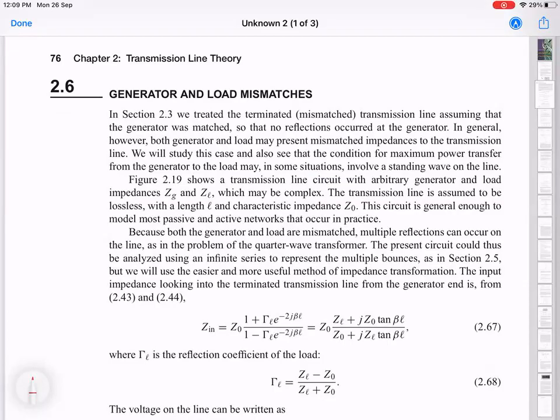So I want to finish up this basic discussion of how we think about waves propagating on a line today, and then introduce you to some of the standard transmission lines we use in practice, what they are. And then in the next lecture, we will go into a little bit more detail in the physics of those structures in terms of Maxwell's equations, simplify them for the particular case, and then we see how one can extract the relevant quantities, which is basically the inductance per unit length and the capacitance per unit length, given the geometry and the properties of that structure.